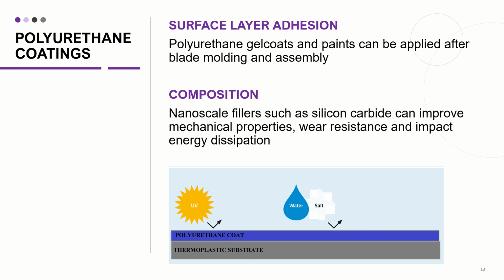For the coating layer itself, thermosets are popular because their cross-linking adds improved wear resistance. However, they require high curing times and cannot be repaired. As an alternative, thermoplastic polyurethane is also highly fatigue and impact resistant. Polyurethane also cures more quickly than epoxy and has a low exothermic energy release, which makes it ideal for bonding to the blade material.